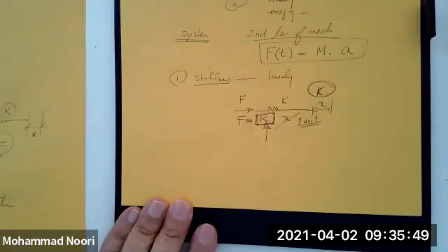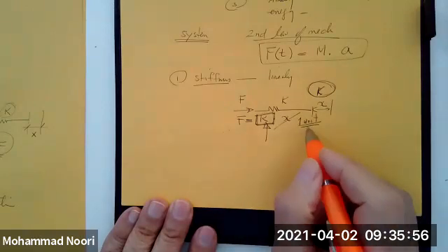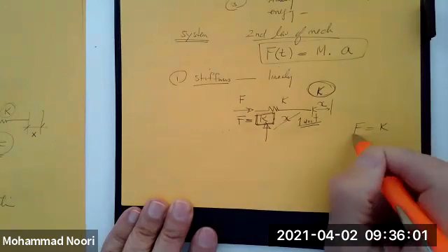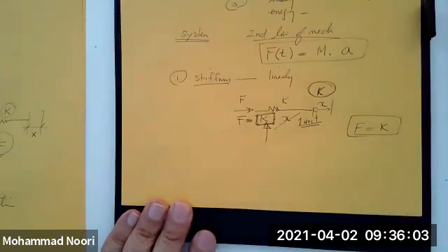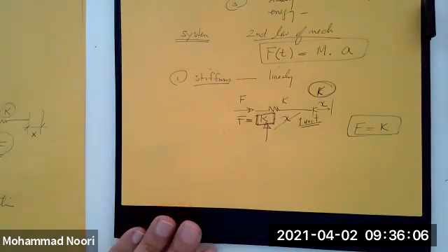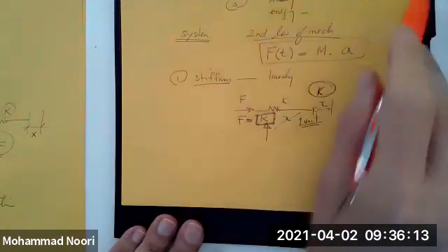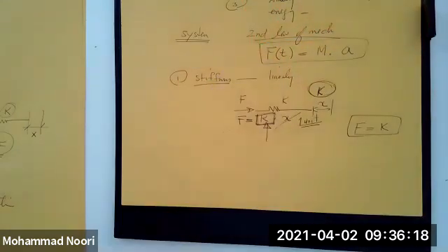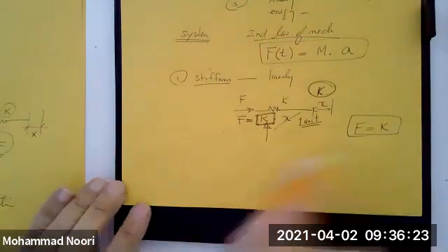In other words, if you apply a force in a system that causes a unit displacement, that force is the stiffness of the system, and you can measure that. We get to that in more detail. But as far as studying the ability of the structure to resist deformation, we need to understand what a stiffness is.